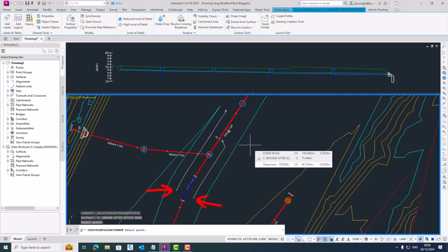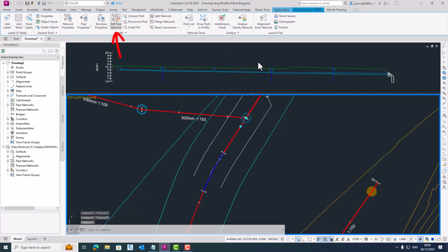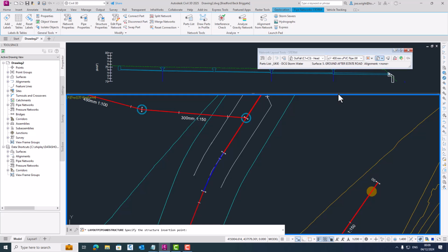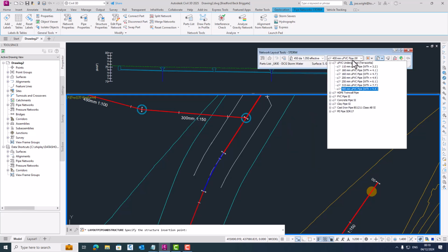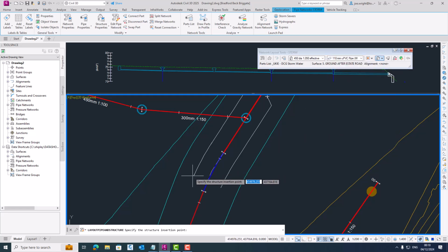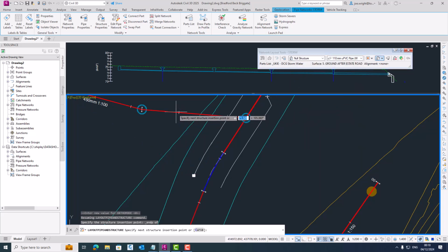are both contenders for gullies. Let's put them in. Clicking the existing pipe network will allow us, by selecting Edit Pipe Network, to get back into design mode. This time I'm going to add a gully and a small diameter pipe. Yeah, I can snap the gully to the depression point, but I'm going to add an underground connector. To do this, select null structure. Otherwise, it'll just put another gully in.